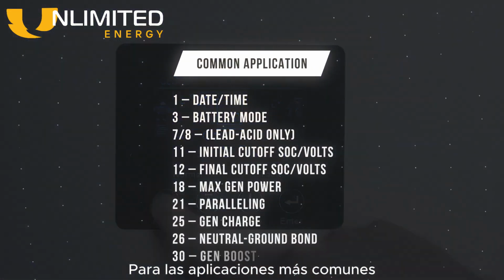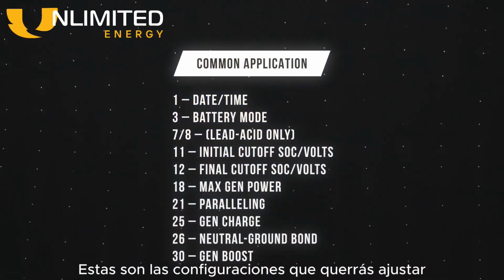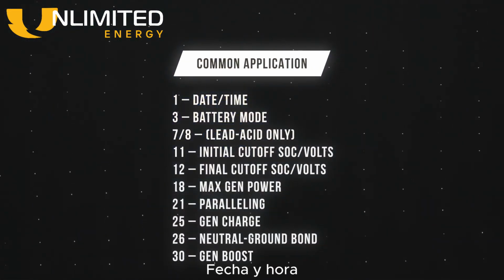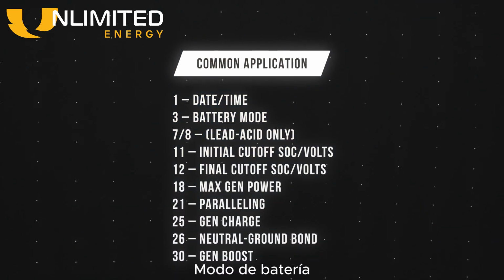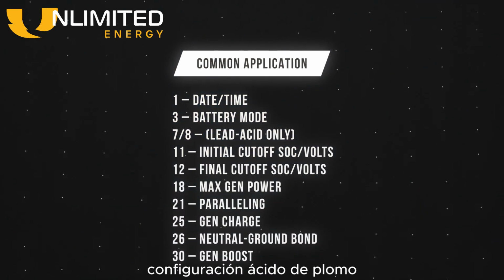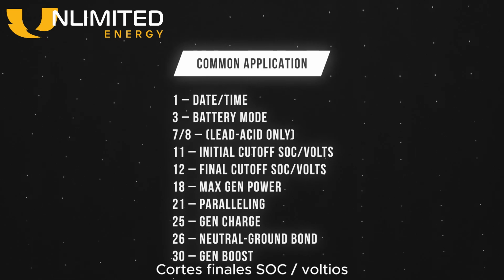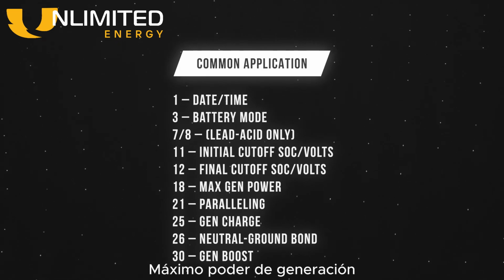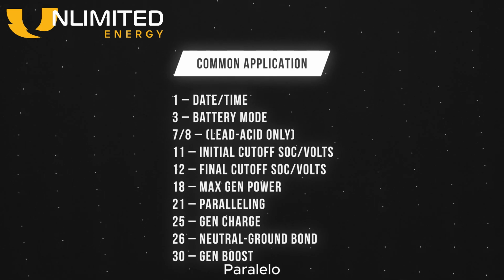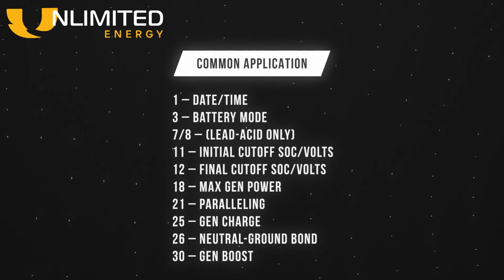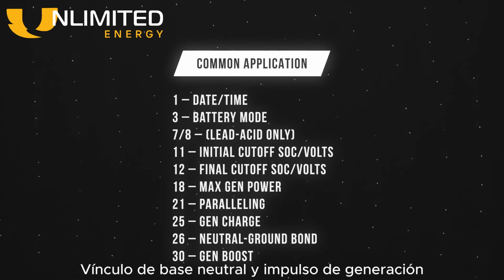For most common applications, these are the settings you'll want to adjust: date and time, battery mode, lead-acid only settings, initial cutoff SOC/volts, final cutoff SOC/volts, max gen power, paralleling, generator charge, neutral ground bond, and Gen Boost.